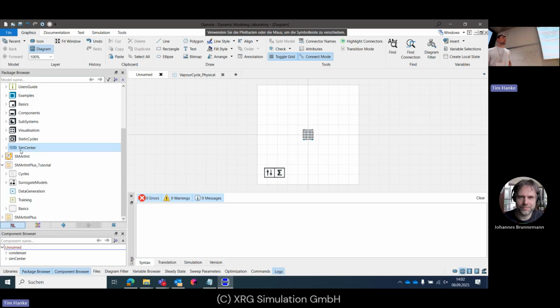Those are gas connectors for air side. And at the bottom are blue connectors. These are VLE interfaces. VLE is vapor liquid equilibrium, and this is what our CO2 model is defined as. It's obviously a gas, but in this case it's defined as VLE.